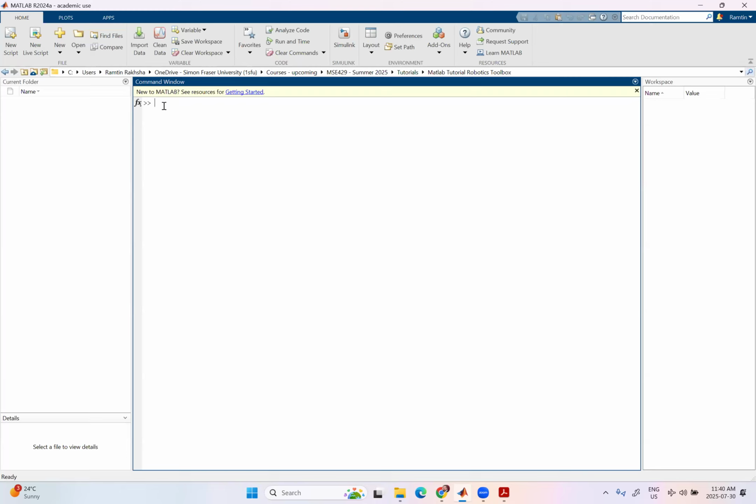One of the first things to do is there is a function in MATLAB that's called importrobot, and the URDF library that's available in MATLAB, we will look it up later on. But there is a function called importrobot, and you would write that in your command window, and then you can import any type of robot that is out there. IIWA14 is the 7DOF robot that you would want to import here. URDF, look at that. Either I just call this importrobot function, or maybe I'll assign it to a different variable.